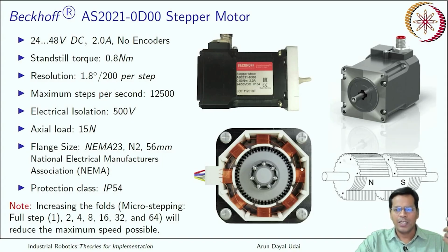When you see, you have a smaller number of armature poles as compared to the number of stator poles all around. Okay, so yes, it can move at very small angles. That is the reason it is able to move at 1.8 degrees. But doesn't matter, even this motor follows the principle of a bipolar stepper motor. It has 4 wires, and the same way you have to shift your poles. So nothing to worry, the same drivers are suitable for this as well.